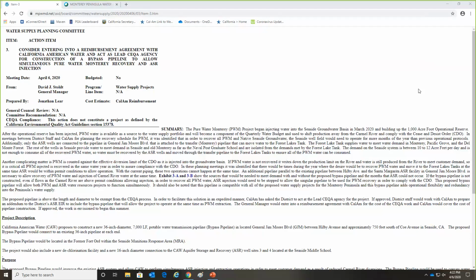Previously, when we had desal coming through the shared pipeline, you had flexibility in terms of ample supply that could be injected and stored. This provides a different means to do so while we do not have desal. So it is a different circumstance in a way than previously under the water supply project. We're looking to maximize ASR while all we have is Pure Water Monterey sources.